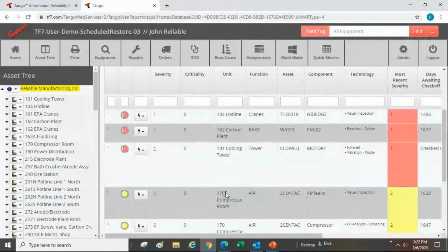In fact, this dashboard, for most of the customers we deal with, is a very useful tool in their semi-monthly review meetings between maintenance planners, reliability technicians and engineers, and operations in making determinations about what the priorities ought to be on the work order scheduling. Let's just say in this case that even though I'm seeing this current case of that motor had clogged cooling fan ends and perhaps that has been the reason that we developed some bearing failure problems, maybe I want to get a little more history.